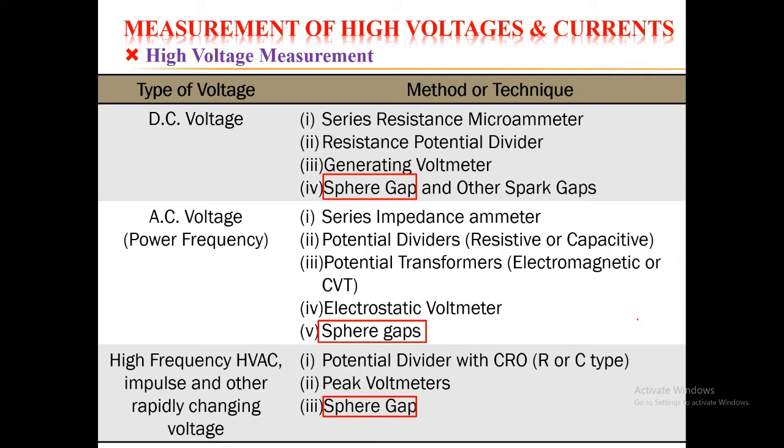But in the case of breakdown, the breakdown is always initiated at the maximum value, or the peak magnitude, of the voltage. So the testing engineer has to define in the report the peak magnitudes at which flashover may arise while testing is conducted on the insulations or high voltage equipment.